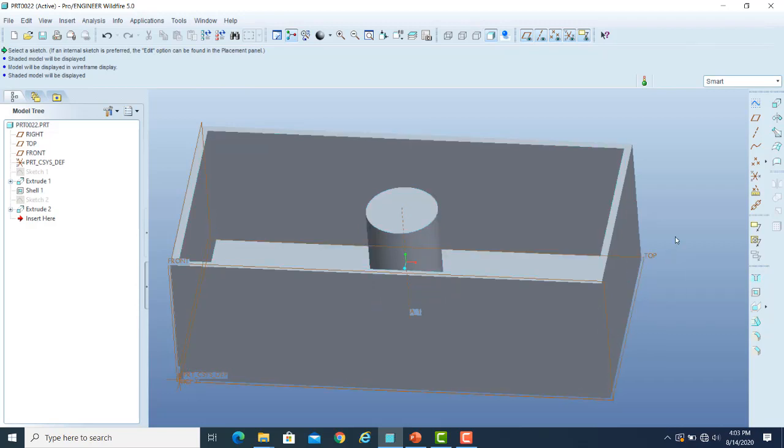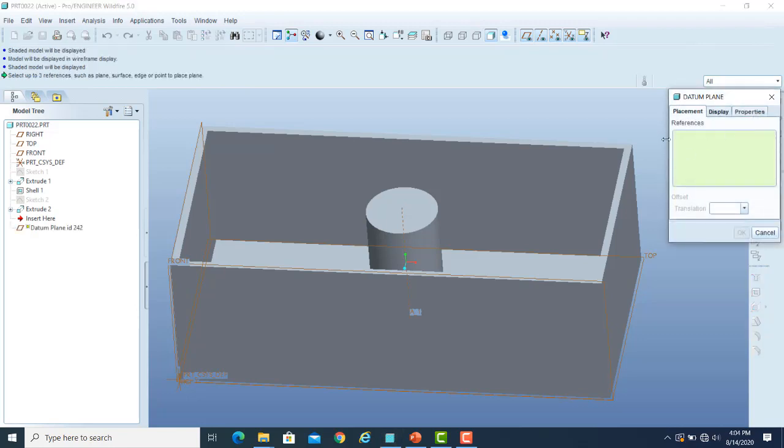So what you will need to do is that you will have to define your own sketching plane. So जो datum planes का option हमने last video में किया था, I will do that. If I click on the plane tab and it asks for the reference, this can be my reference, this axis. If I click on that axis, now I have a plane which is passing through that axis, and now I will fix the orientation at that desired location, जो भी location मुझे चाहिए.